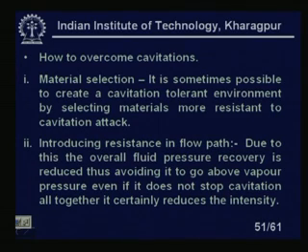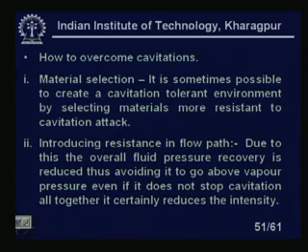Due to this, the overall fluid pressure recovery is reduced. Obviously, there is a pressure loss. This pressure loss will lead to more pumping cost, obviously, but we can avoid the cavitation. Introducing resistance in the flow path reduces the overall fluid pressure recovery, thus avoiding going above the vapor pressure. Even if it does not stop cavitation altogether, it certainly reduces the intensity. Intensity of the cavitation will be reduced.